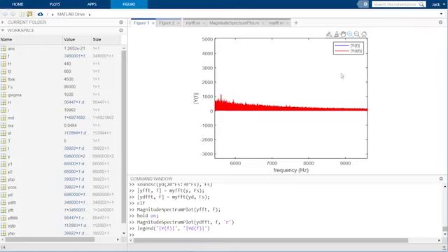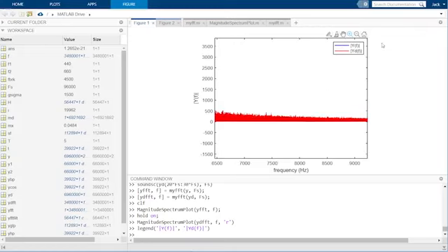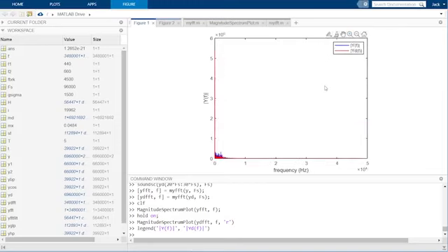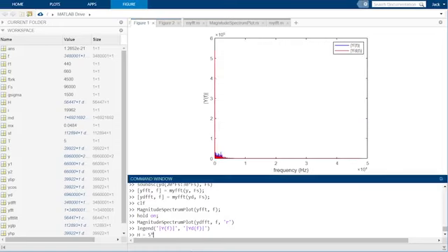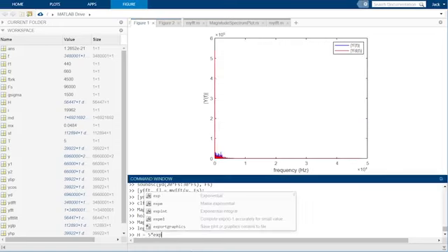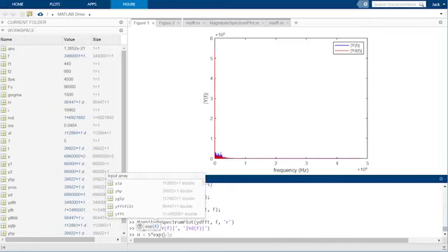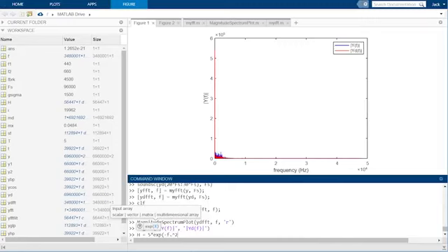So we can try to clean this up a bit by doing some low pass filtering and low frequency amplification. So let's create a Gaussian filter with a sigma equal to 3000. And we multiply it by 5 so that the filter actually amplifies the low frequency content.